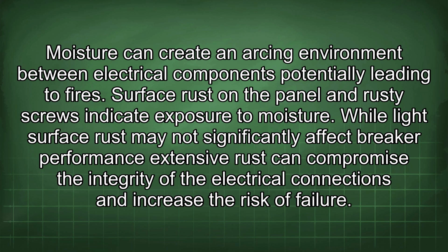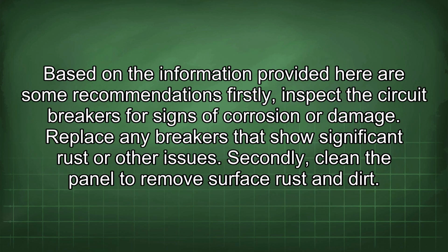Surface rust on the panel and rusty screws indicate exposure to moisture. While light surface rust may not significantly affect breaker performance, extensive rust can compromise the integrity of the electrical connections and increase the risk of failure. Based on the information provided, here are some recommendations.